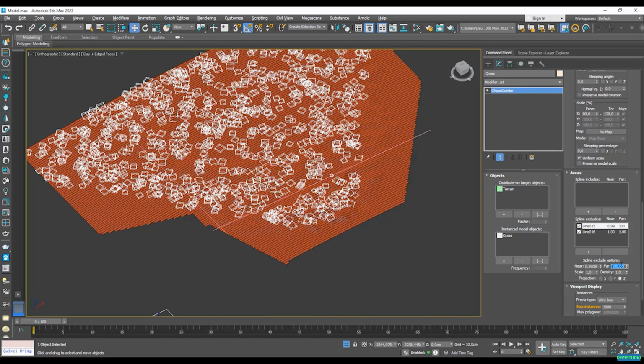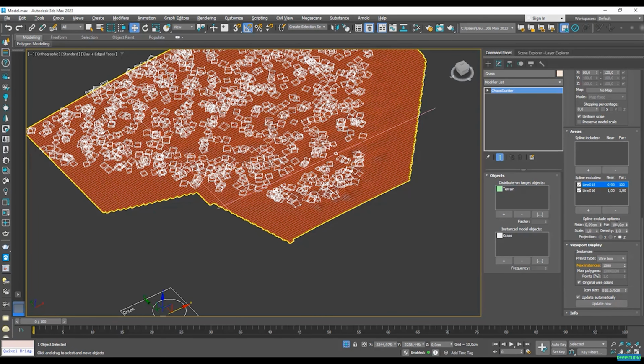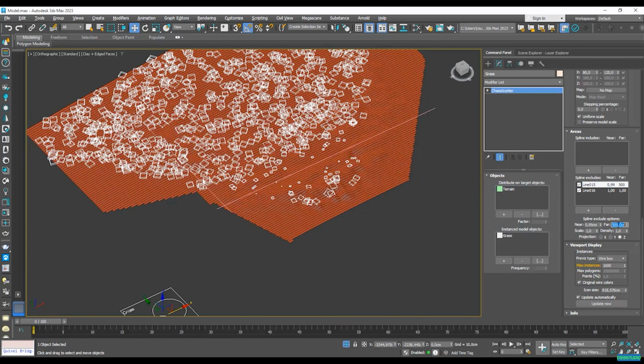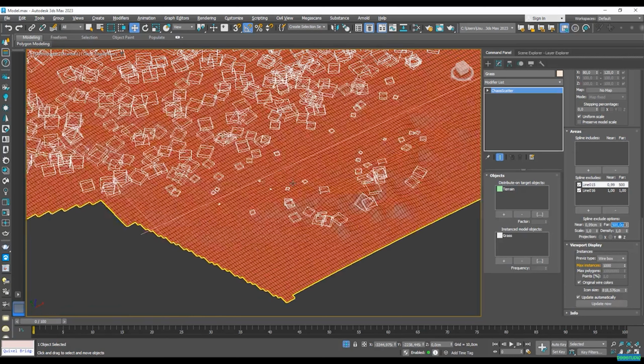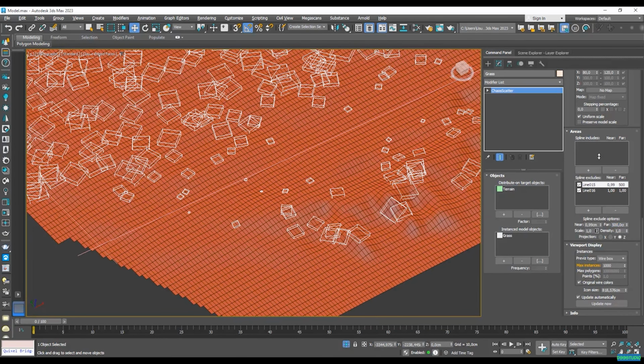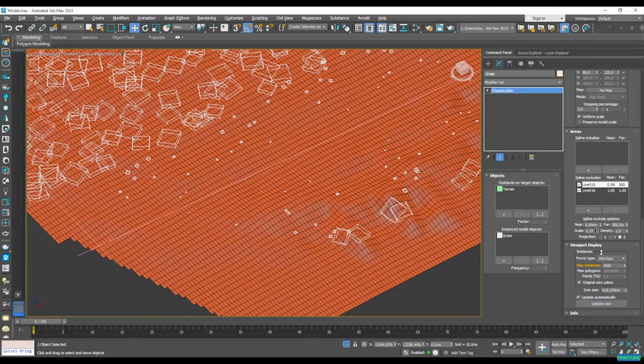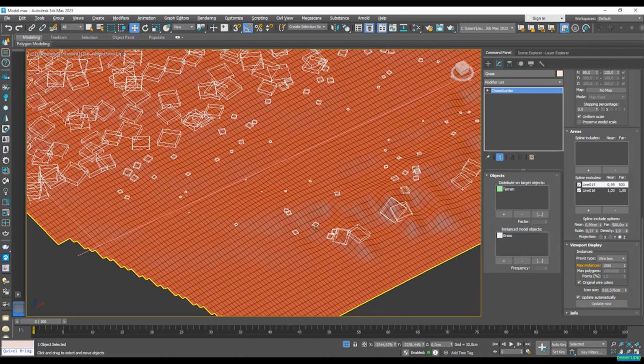This means that we're going to be creating a 1 meter invisible offset parallel to our line in which the grass will not be distributed. So let's go ahead and say 500 centimeters. And you can see that the grass starts to get smaller and smaller. If I also start reducing the scale from the grass, I'll be making this exclusion more noticeable.